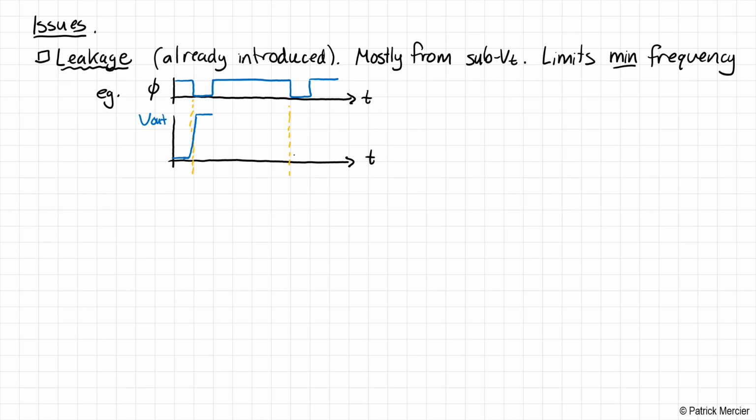And then when the clock gets released and the pull-down network is not active, because of leakage, we're going to start trending downwards here. I'm going to say that we want to make sure that we don't pass some threshold limit. This is debatable what this should be, but let's just say for this example, we don't want to cross VDD over 2. Because if we cross past VDD over 2, then we've definitely lost our logic value.